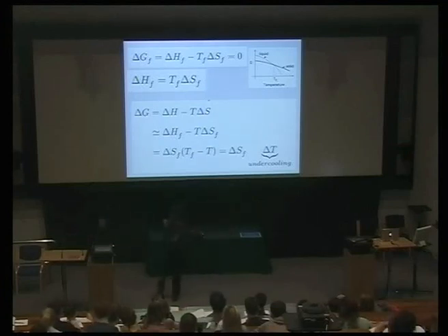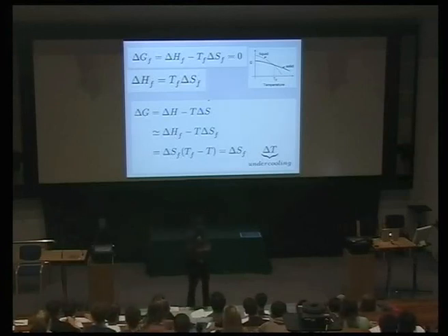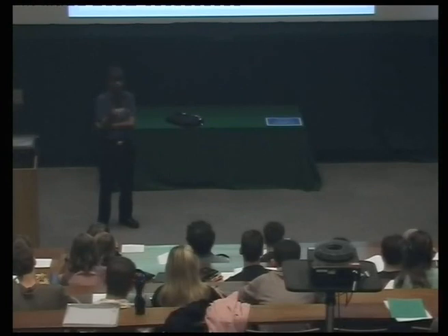Okay, so here's another question. Why doesn't solidification start the instant the system goes below the fusion temperature? What is necessary before solidification can start? That's right. So we have nucleation to cope with. Nucleation involves the creation of a new surface, and that requires a certain amount of undercooling.